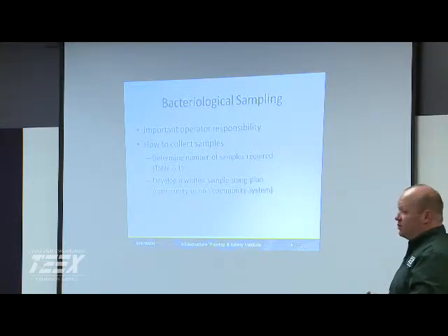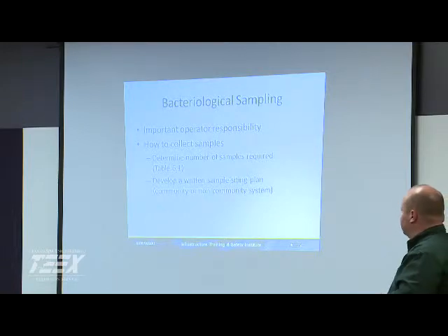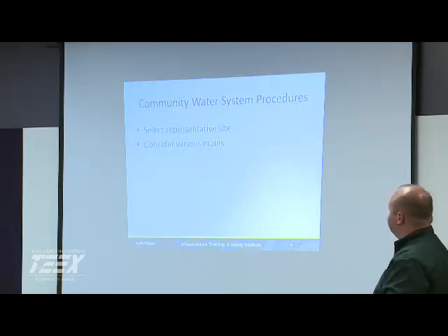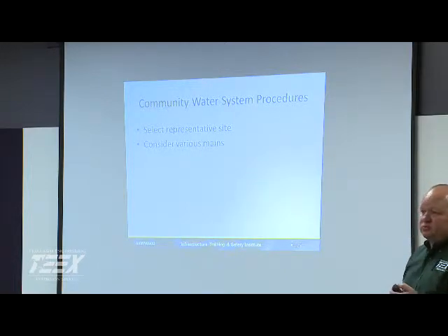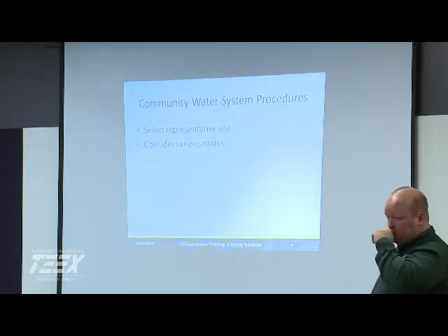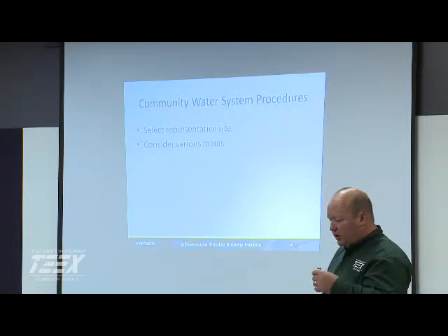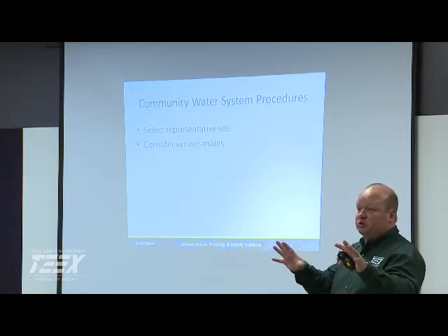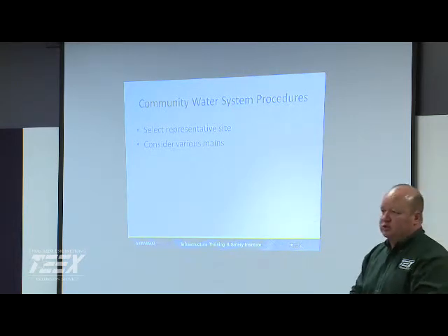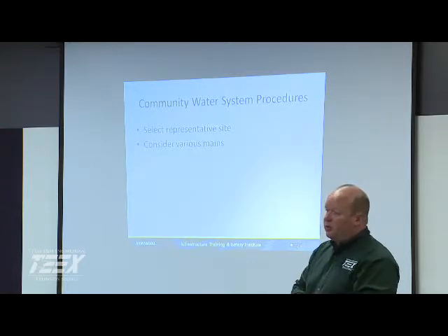Yeah, consistency is really important in your sampling, in your locations, in your techniques. So we talk about representative sites. We do need to look at our distribution system, looking at our maps and seeing where we might have issues with water age. AWWA did a neat article not too long ago on hydraulic modeling of distribution systems, looking at water age, because water age plays into a lot of water quality issues. Your chlorine residual issues, disinfection byproducts.